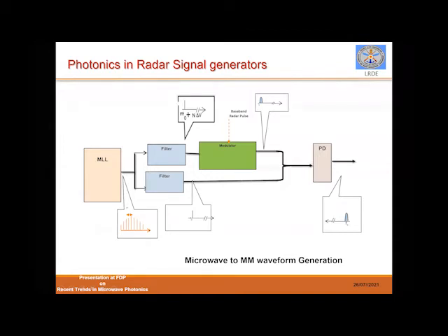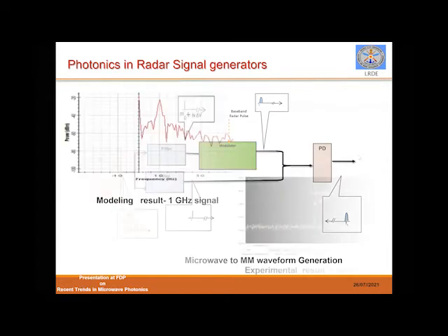So the same method, and if you search on the web also, those who are working in the microphotonics region, you will agree with me that there are photo detectors or RF receivers, a single one of which can operate up to, some are offering up to 25 gigahertz, some are offering up to 18 gigahertz, some up to say 10 gigahertz. So the same architecture can be used for the generation of RF in L, S, C, X, any band. Okay. So the same architecture is enough.